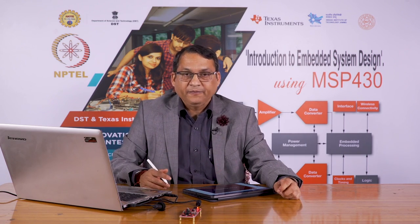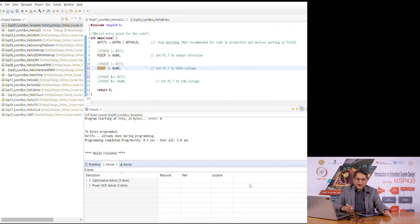Alright, so what I have here is my laptop and I have opened the Hello LED program. You would have downloaded it from the Git repository and you would see a program called Hello LED. I will go through that. So, the first part of the program is talking about including msp430.h. This is a header file which has useful information such as the bit mask and so on. Then you have the main code.